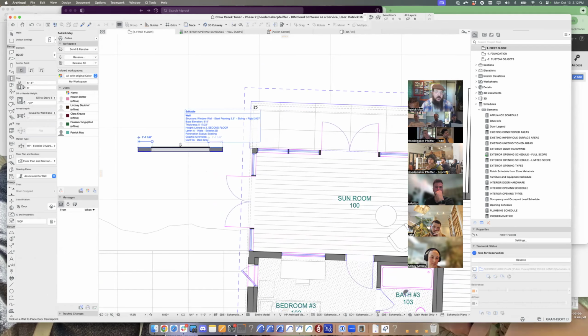So there is, it's based on when you first place the door or window. So if you notice, like here on my cursor, when I'm about to place this door into this wall, I get the little sun icon, right? That's so all doors and windows have an interior and an exterior setting. And that's for interior surface, interior trim profiles, jamb extensions versus exterior trim profiles, surfaces, etc. Unfortunately, there's nothing that indicates which side is interior versus exterior after you've placed it. So it is a bit of a guess and check thing.